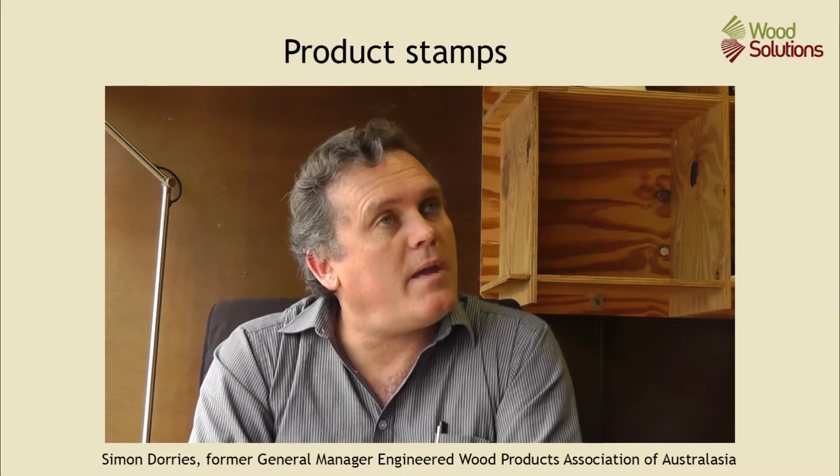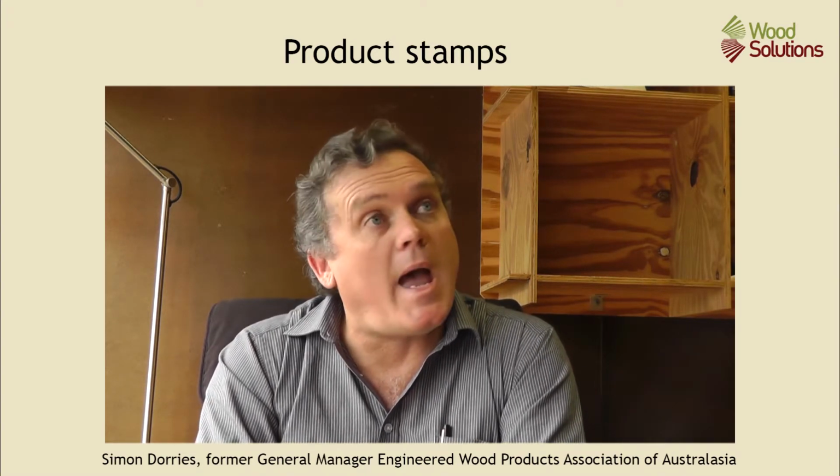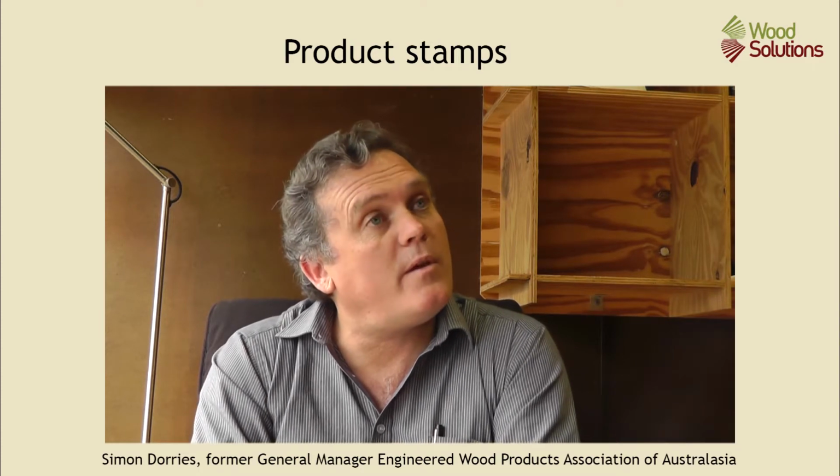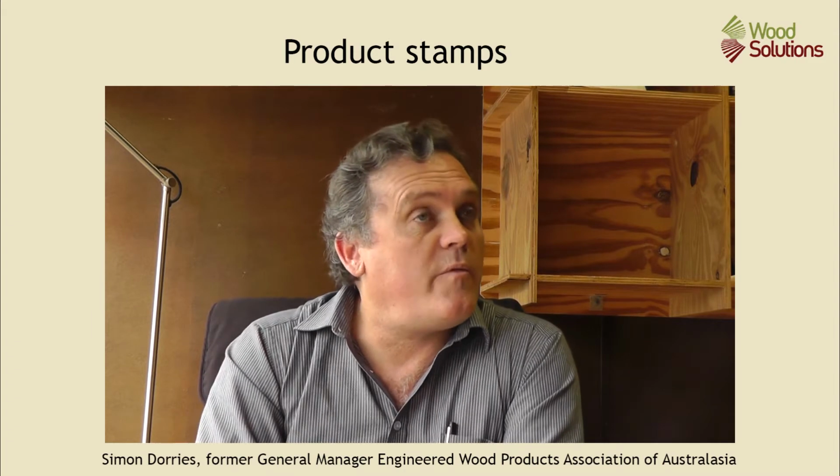Secondly, you will have the face and back veneer grade. So you'll see letters, for example, C, D. It means that the face grade is C and the back veneer is a quality D. Marine plywood, for example, will be AA. It means that there's an A grade veneer both face and back. You'll also find the stress grade. So with structural products, it's absolutely critical that you use the correct stress grade, or potentially you could have product installed that's not adequate for the job and won't carry the structural design load. So very, very important.